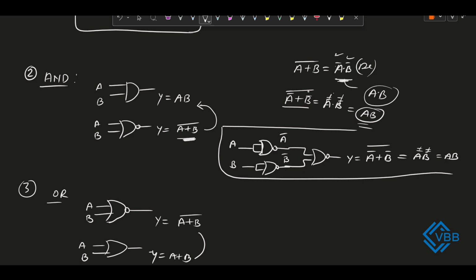Okay. So what we need to do, just we need to connect this output to a NOT gate to get the OR gate expression. Okay. So we have seen here in the last implementation how to treat a NOR gate as a NOT gate. So from that concept we will get the OR gate expression. So here we will get A plus B complement, and that will come again to a NOT gate, and that will cancel out, and we will get a final expression as OR gate.